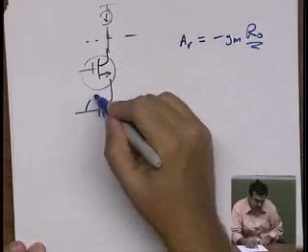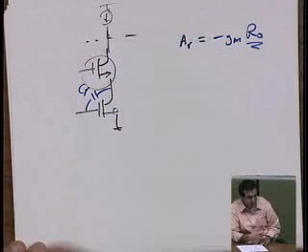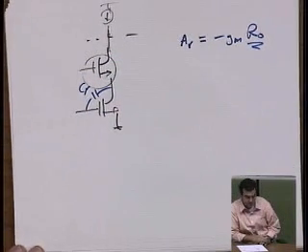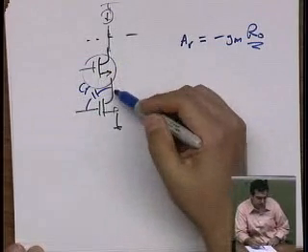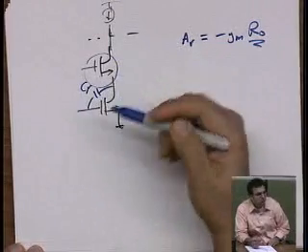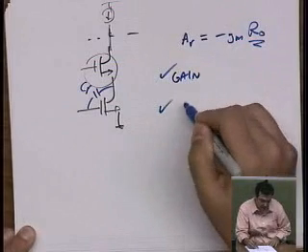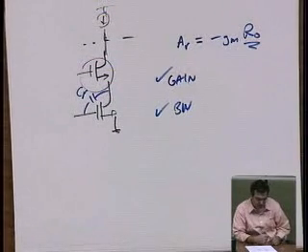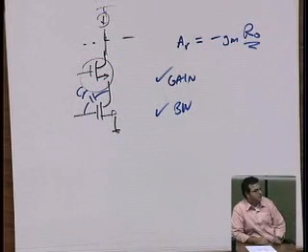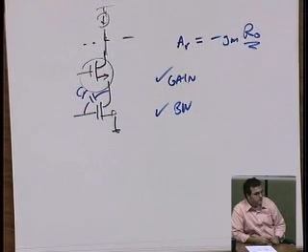We know that in a common source amplifier we've got C mu, Miller effect, and so if we have a large voltage gain, we pay the price with bandwidth if we're driving with any input source resistance. Here, because this buffer stage keeps the internal voltage gain low, there's very little feedback, and so this is actually a very broadband amplifier. So it's got gain, it's got bandwidth, and what's a third advantage? Yes? It has good power supply rejection. Okay, and that's again because of the unilateral properties.